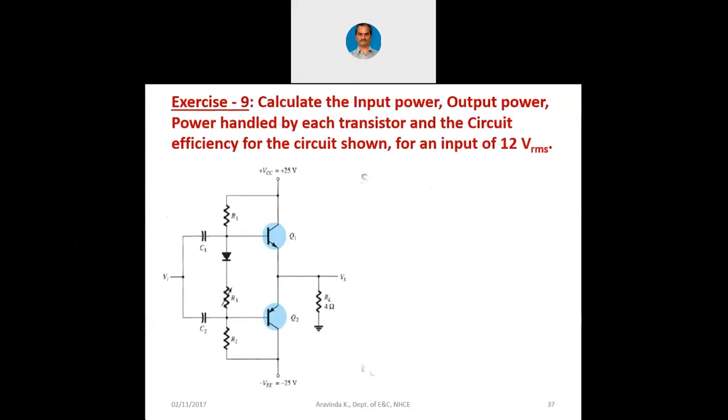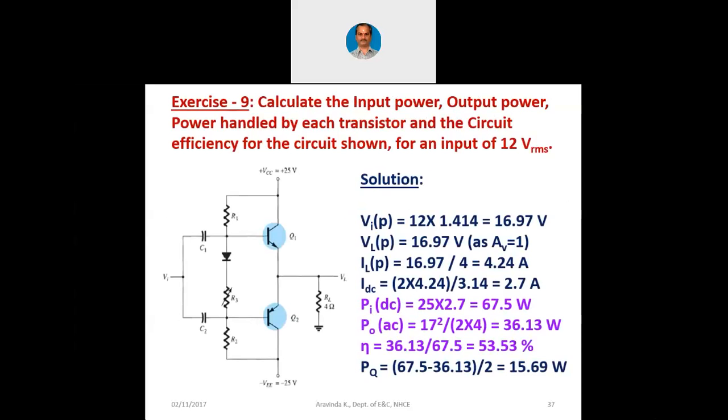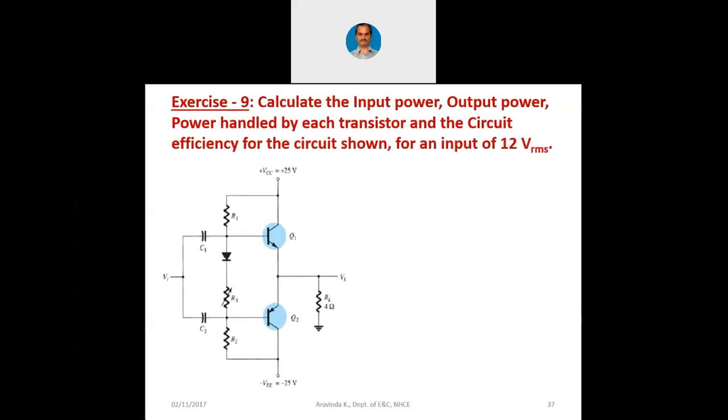I am showing you the answers now. Before that, there is this diode here and there is this R3 here. Now the diode is also there because in this case, it is not a Darlington transistor or Sziklai pairs usage. Now they are single transistors. So as far as VBE is concerned, there can be a difference between NPN and PNP itself. That is one point. Second point is always the mobility of charge carriers in case of PNP is lesser when compared to that of NPN.